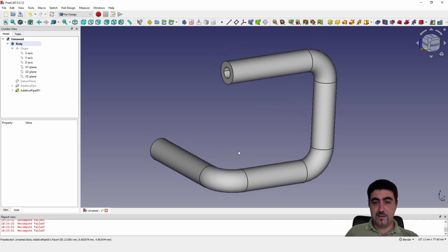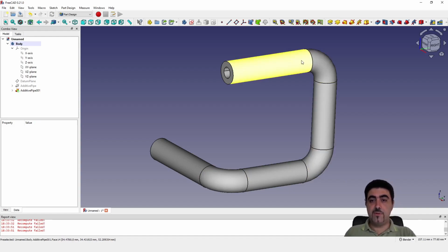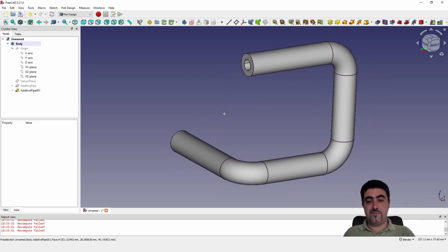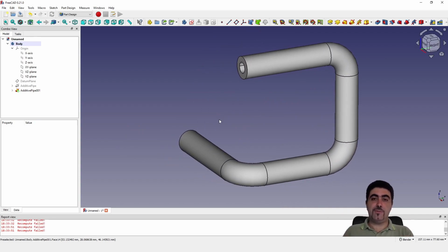And you also saw that it doesn't need the sketch as a sweep profile. It's happy to take a face. So you can create the exact same shape, parametrically defined again, and yep, that's how you would do it in FreeCAD.